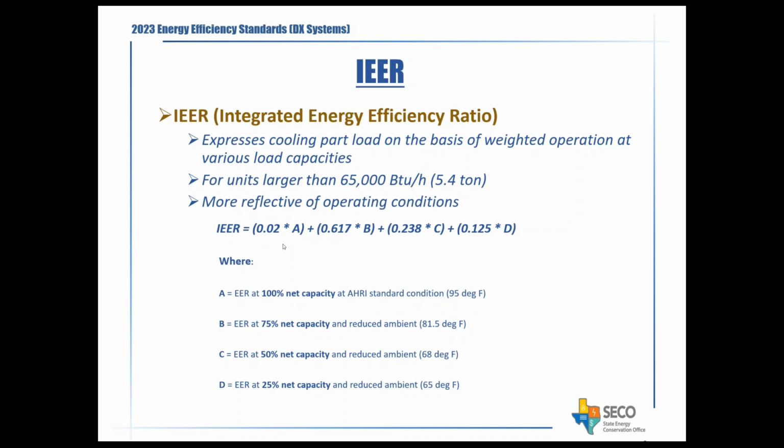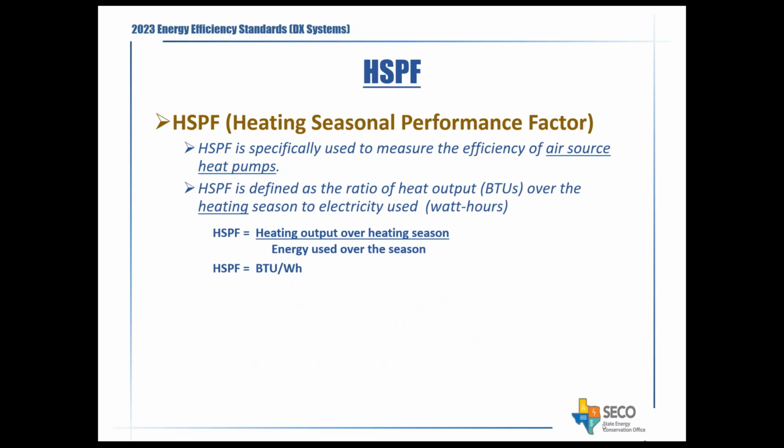So that's something to keep in mind. Before, the EER used to be just one number at a particular condition, which was 95-degree ambient. The IEER is more the weighted average of it at different conditions.